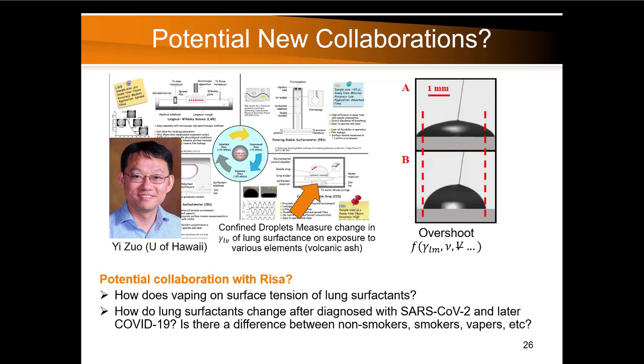Since no one is asking any questions, and the call hasn't come in yet, let me ask you a question here. How much contact angle change can you accomplish given any choice of material and liquid? That is a good question, Satish. I think this is why we put the hydrophobic surface down. The higher your initial contact angle is, the more change in contact angle you can get.